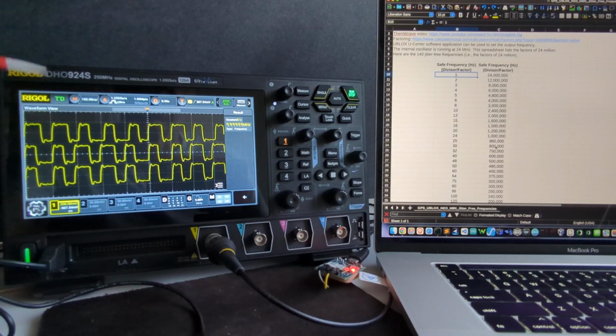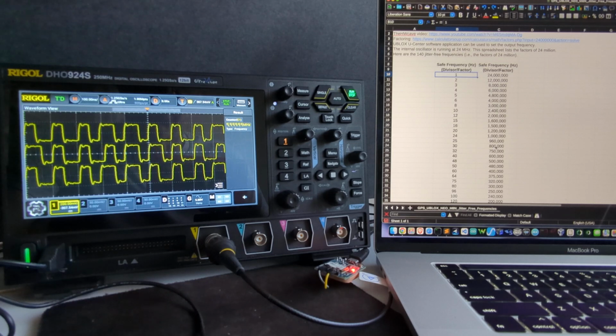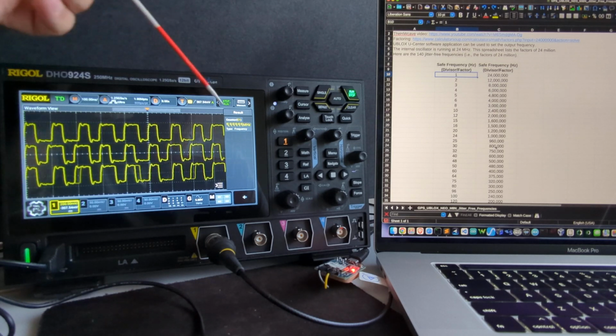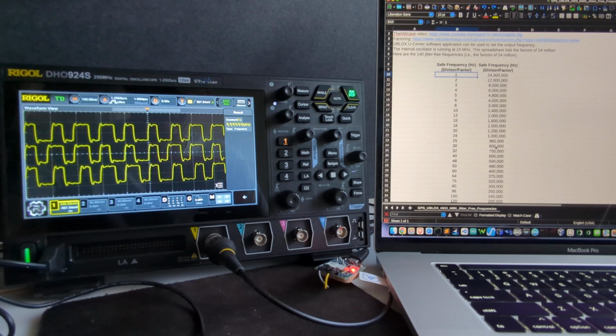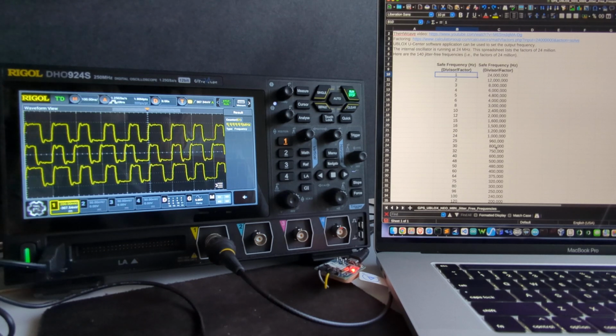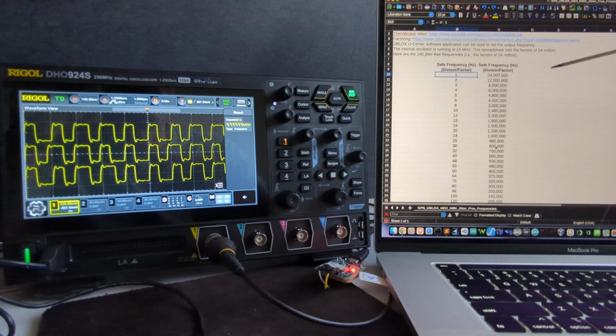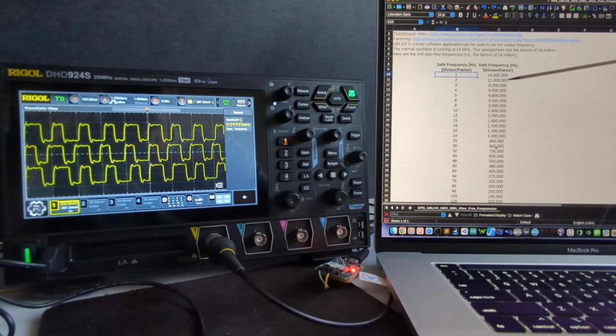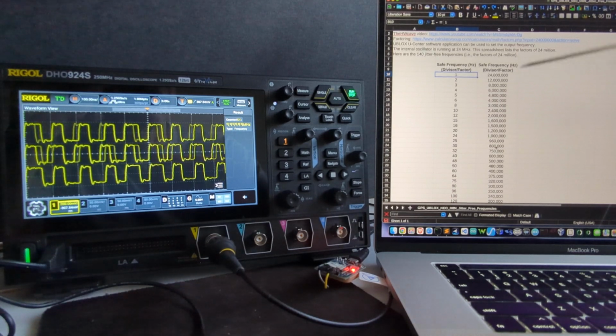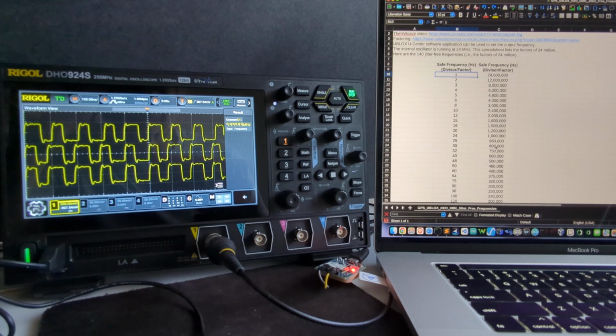So that's why we're seeing all this, what would be referred to as glitches or jitter in the output. It's actually just the software saying, I need to deliver 10 million waveforms per second. And this is the way that I can do it, because I can't deliver one particular waveform consistently across that 1 second time period. So I have to mix the 12 megahertz with the 8 megahertz. And so that's what that looks like.